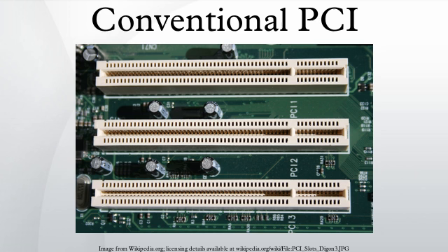To get around this limitation, many motherboards have multiple PCI/PCI-X buses, with one bus intended for use with high-speed PCI-X peripherals, and the other bus intended for general-purpose peripherals. Many 64-bit PCI-X cards are designed to work in 32-bit mode if inserted in shorter 32-bit connectors, with some loss of speed. An example of this is the Adaptec 29160 64-bit SCSI interface card.